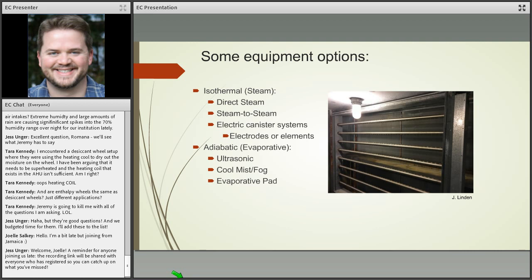And these are various types of acids that get added to the water stream itself. The problem when you use that direct steam to humidify is that you're pushing that steam into the space containing the acid that has been added to the system in order to keep the boiler clean. That's great for the boiler. It's kind of lousy for your artwork.